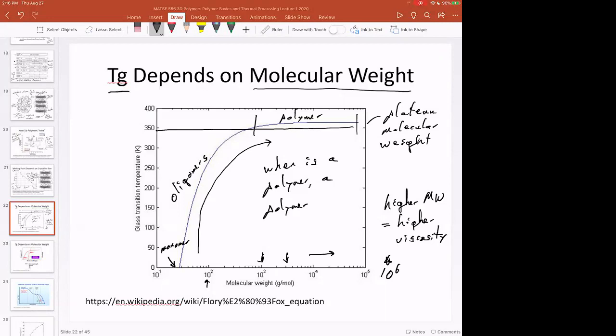And so when people make things like Spectra fibers, which are ultra high molecular weight polyethylene, or you're making hip sockets or medical implants from ultra high molecular weight polyethylene, they're doing that for a reason, to get the properties they want. But most polymers that you buy on the open market for injection molding or extrusion or blow molding or something like that all have a molecular weight that's tuned to get the properties that people want in their final products, but not have to deal with these really high viscosities.